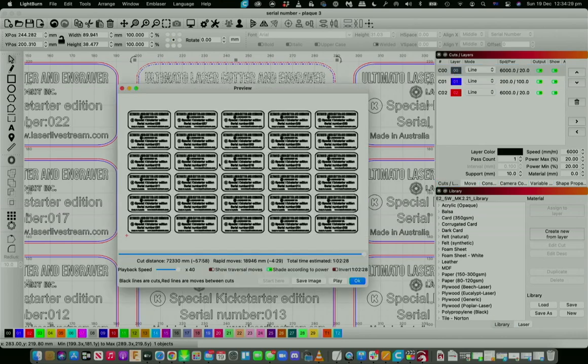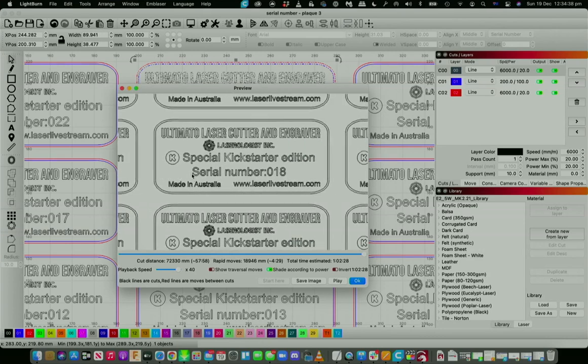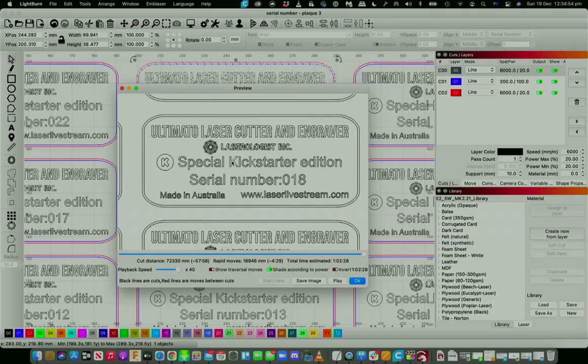So if we take a look here, what I've actually done is use the lines, and then we haven't actually used any fills. I can buy material that has a very thin color on the top and a separate color underneath. So the laser, when it's actually going and engraving this as a line engrave, it'll actually reveal a black and maybe a red surface or a blue surface or a green surface that produces a very, very good result. So I'm setting this job up with that outcome in mind.